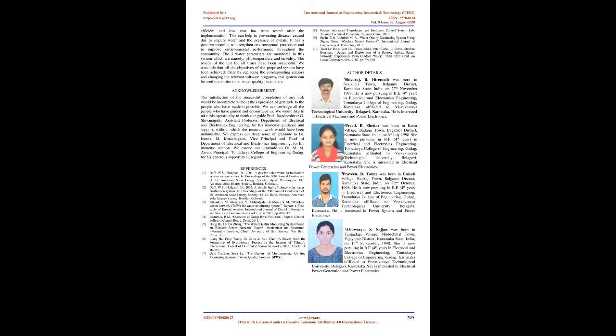Before purification, the water parameters are not meeting the standard values of pH, temperature, and turbidity. After purification, the water parameters are nearly equal to the standard values: pH around 6.5 to 8.5, temperature between 20 degrees C and 30 degrees C. The turbidity of water will be around 0.5 NTU to 1 NTU, which can be measured from the experimental results, and it is fit for drinking purpose.